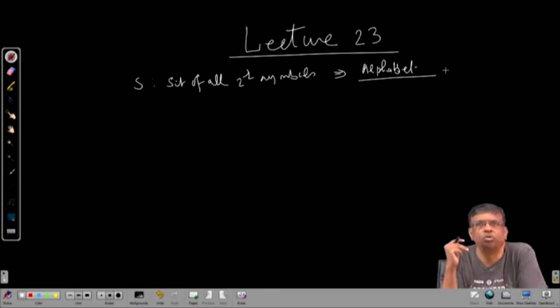They can carry analog waveforms. We can give an analog waveform at the input, it will go through the analog channel and you will get some analog waveform at the output. But they cannot take discrete things, like 5 volt, 10 volt, 4 volt, not like that. So therefore, for the symbol I have to have some pulse, a basic pulse, and that will carry on its shoulder this information about the symbols.